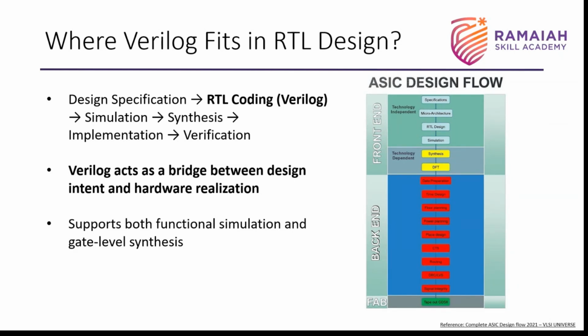Once you have designed the RTL code, then you simulate it. That is, you verify whether whatever you have done is correct or not, and that your chip works as per your requirements. Then you generate, from the code you have written, logic gates. Because at the end, what we see on the chip is nothing but the gates. So you have to convert your code into logic gates. That is what is called synthesis.